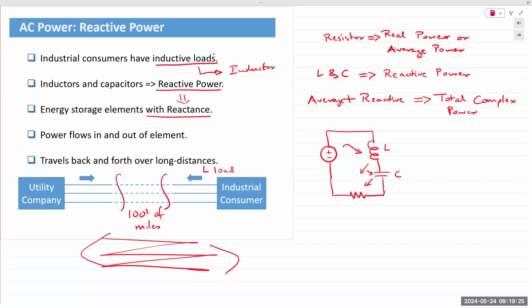The energy that is being transmitted, we can separate out into two components. The energy that is required to perform the mechanical work, which is the real power, and the energy that is associated with the reactance, which is reactive power. They are not two separate things. When the utility company sends a voltage or current, it sends the entire amount that is required to get your electric machine started up and going. Depending on the design of the machine and the values of the components, maybe 50% is used for real, 50% is used for reactive, perhaps. It's all transmitted as one piece.